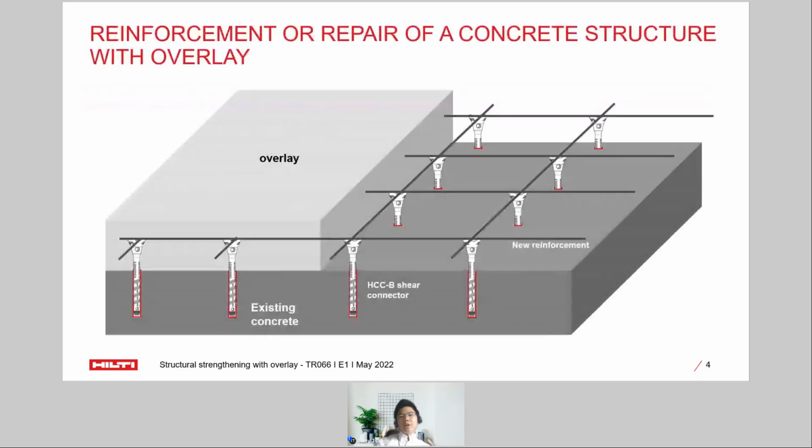When we are strengthening an existing concrete structure by adding a new concrete layer to the existing member, it is very important that we ensure a monolithic or composite behavior of the concrete cast at different times. It can be achieved by designing the shear interface and transmitting the tensile force generated by friction into the shear interface. Concrete overlay is becoming increasingly important due to the growing need for repair work and reinforcement of existing structures. If the shear stresses in the bonded joint between the concrete layers that were placed at different times are not sufficiently transferred, the safety of the structure is at risk.